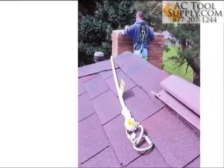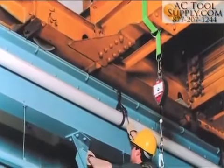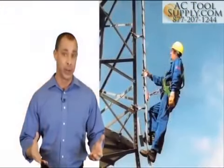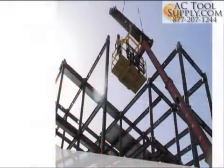To avoid a dangerous swing fall, workers should always try to connect and work directly underneath an anchorage point whenever possible. An anchorage connector is an intermediary fall protection device, such as a cross-arm strap, D-bolt, or rope grab that links the worker to the anchor point. Anchorage connectors are offered in a variety of configurations to accommodate vertical or horizontal connections for attachment to concrete substrates, large and small beams or scaffolding, rooftops, and structural steel.